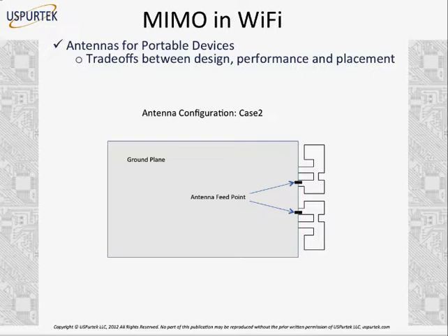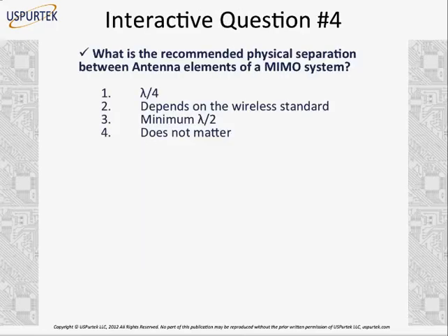So although you sacrifice diversity a little in this case because the antennas are closer now, you gain advantage in other ways, like your feed points are closer, so your losses due to feed points being far apart are reduced now, right? So again, it's up to the actual device, how you implement this design physically inside the device and which one is best for any particular device. But again, trade-offs are there. You have to trade off one thing with the other.